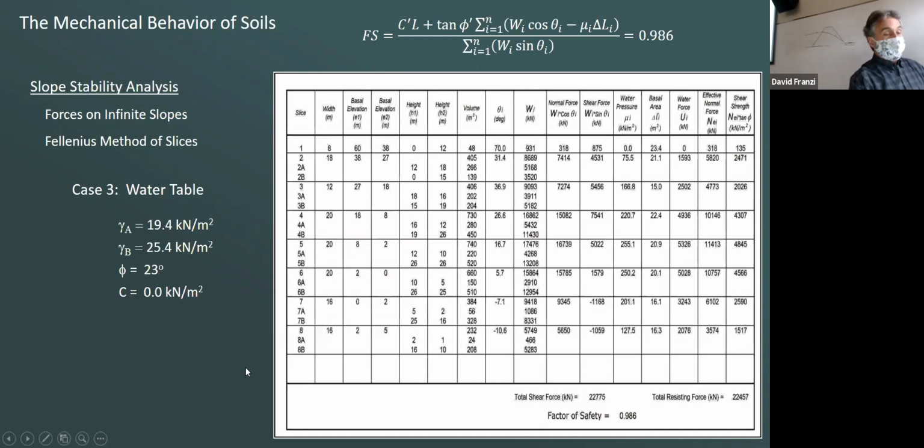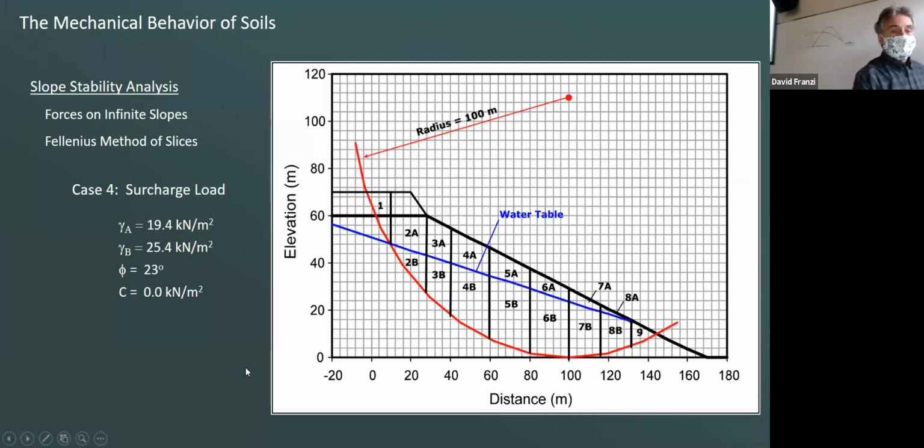So I said, well, okay, I'm not going to cut into the bank. I'm going to put my house at the top of it. So I put a layer of soil up there. I'm going to do some pre-consolidation. That's how we do that. We load the soil and let it consolidate for a period of time so it packs down. So I put a 10 foot layer of soil, so it will pack the soil down for me.